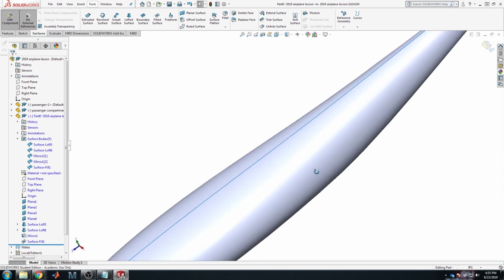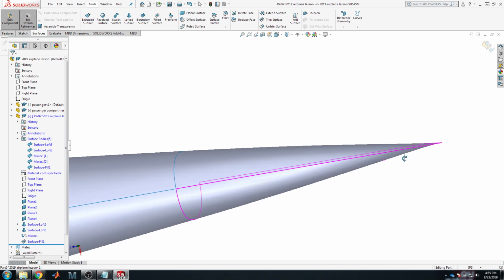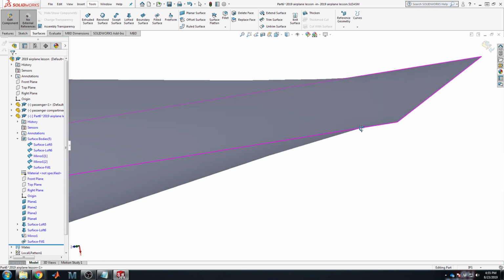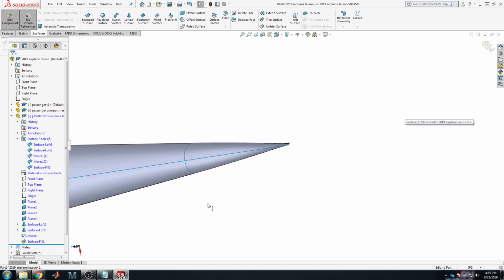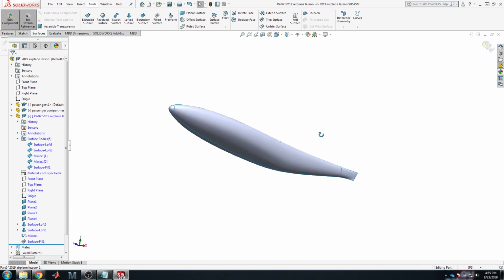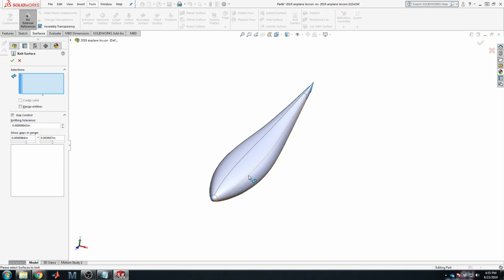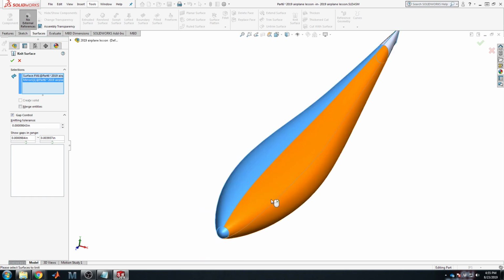Now they match up to one another very, very well because we used these surfaces to create others. So it should be fine. Know that we probably will have some difficulty back here because it's infinitely thin, but we'll solve those problems when they come. You could include some thickness there if you felt like it. Let's go ahead, however, and just finish up this video by saying knit. Knit surface is how you join these multitude of well-behaved, edge-compliant surfaces with one another. You just go around and click on everything you want to join up.